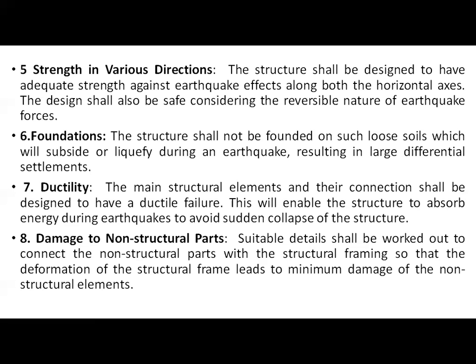What happens first? If water is available at a small depth in the soil, then excessive vibration caused by the earthquake reduces the shear strength of the soil, and because of this excessive vibration, soil and water mix with each other, form mud, and that mud comes on the surface of the earth crust. That is nothing but soil liquefaction. And if such soil liquefaction happens where you built the building, then automatically whenever dynamic loads such as earthquake loads come on the structure, our building will collapse.